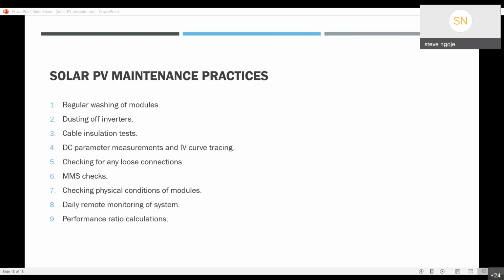Maybe this time someone consumed 20 units, the next time 30 units, then 3 months ago 60 units. So you can't really tell what happened. You might decide to use the highest to design your system, but maybe someone had decommissioned one of the loads that made it go that high.